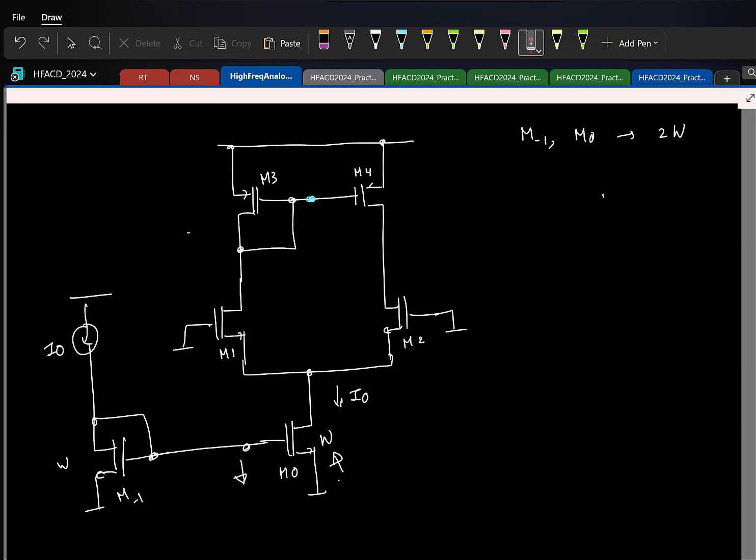That is one thing. And if I increase the size of it, what else will change here? If I have a larger transistor, the capacitance is going to be higher. So let us say the gate capacitance is higher, and even the drain capacitance slightly increases. If this cap increases, is it good or bad? Why bad? Why good?